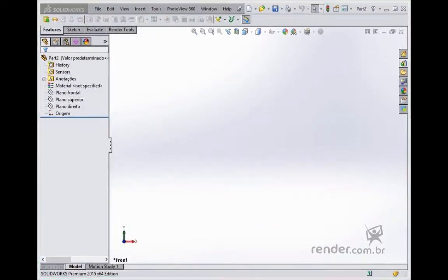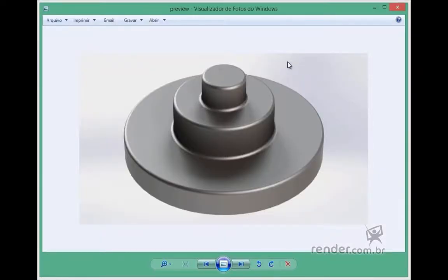Note this part: before you start modeling, we need to define the design intent, that is, what is our purpose or need for this modeling? For example, if this part is used in assemblies, it is interesting that it contains fewer features to lighten it. However, there may be the need to exemplify the manufacturing sequence, if the part is cast or machined. Finally, we need to think before we set the initial profile.